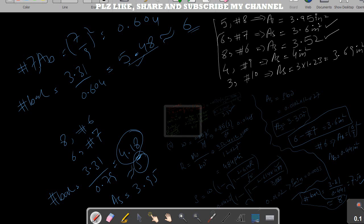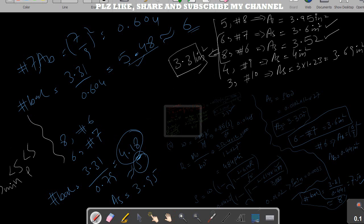These two options are close to 3.31 square inches. So choose the closest one, but make sure that number 6 bar can be justified in the cross section, and it will pass the check that As provided should be greater than As minimum but should be less than As max.